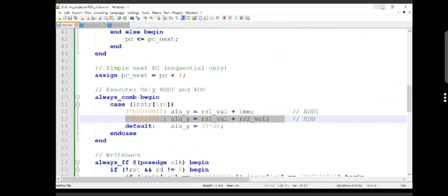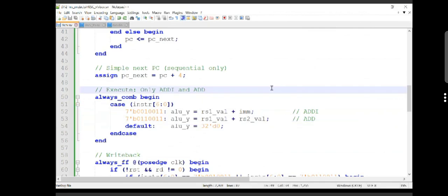So whatever instructions you are giving, according to those instructions it will continuously increment those values. Whatever instruction values you give, it will select the RS1 value, RS2 value, immediate value, everything from your instruction, filter them, take the values and add them. This is what the RISC-V processor is doing. Every addition, subtraction, or any operation coming from your CPU will be done by this RISC-V processor. According to your instructions, it will select this and select that.